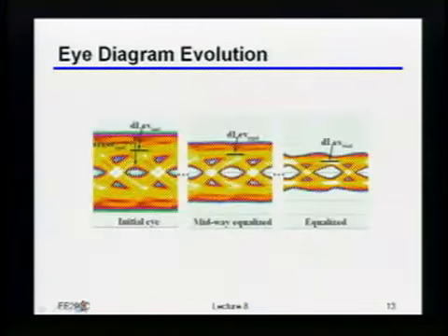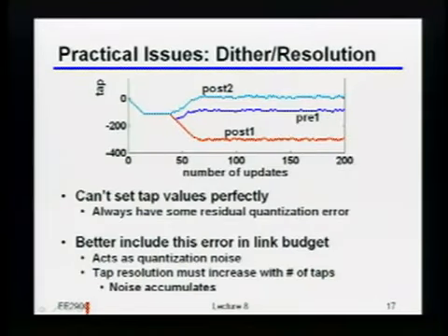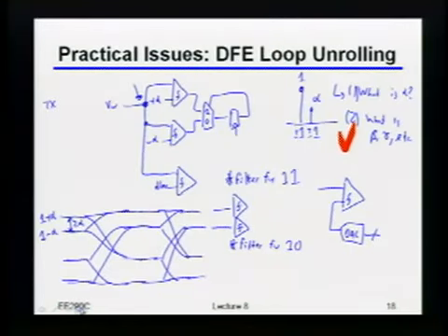So the real reason why, again, I'm actually not the biggest fan of this particular implementation, although sometimes you just don't have a choice, is that if you do this, you better make sure you build a super duper linear offset DAC, and to go along with it, another super duper linear DAC that creates the DFE correction. Because there's no closed loop thing that actually drives you to the right spot. Okay? Yeah? I do have a question about that.